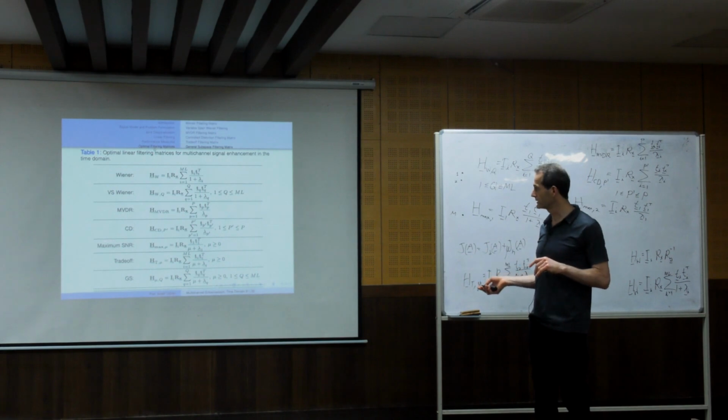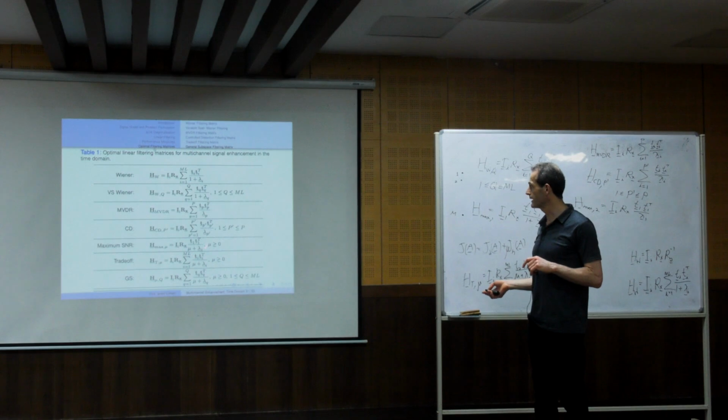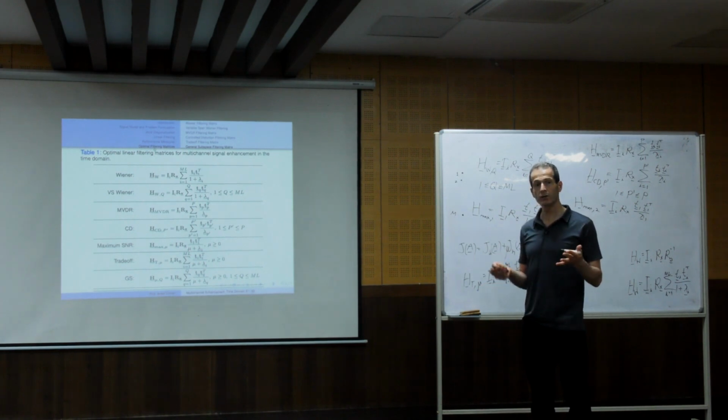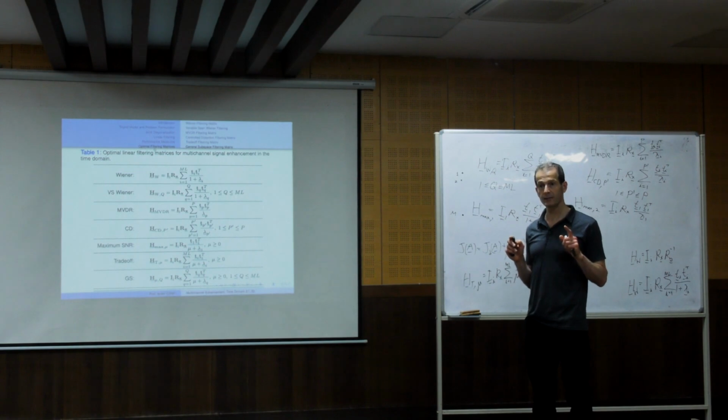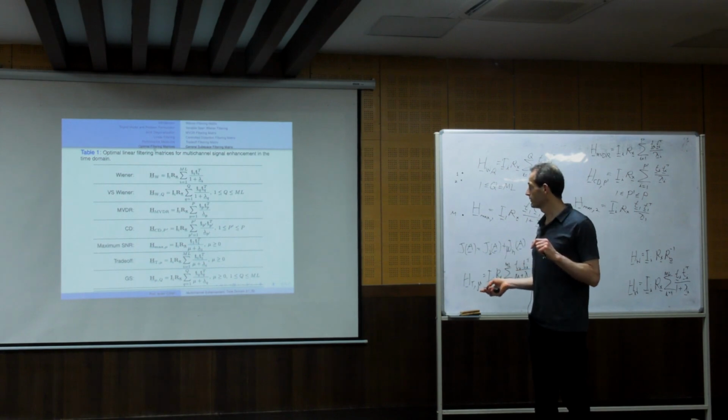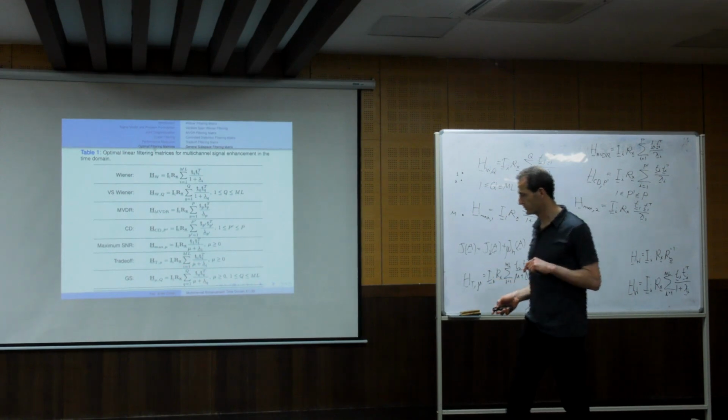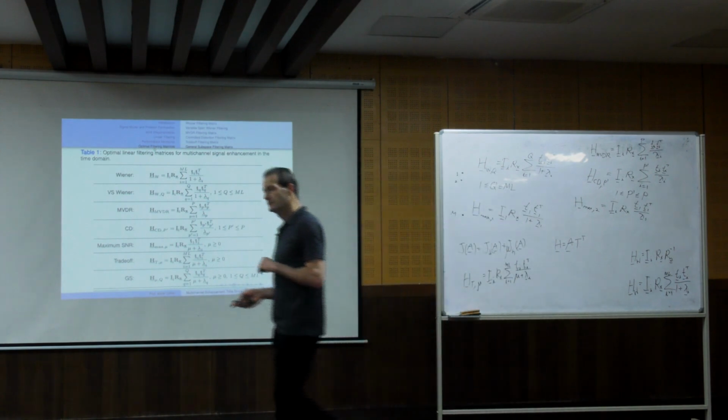So even with the maximum SNR, we can control the trade-off. This is a way to choose the component with the highest SNR, and then we control how much we reduce noise compared to how much we introduce distortion in this component. And we have the more general trade-off, where we choose more elements. This is the general form. Any questions?